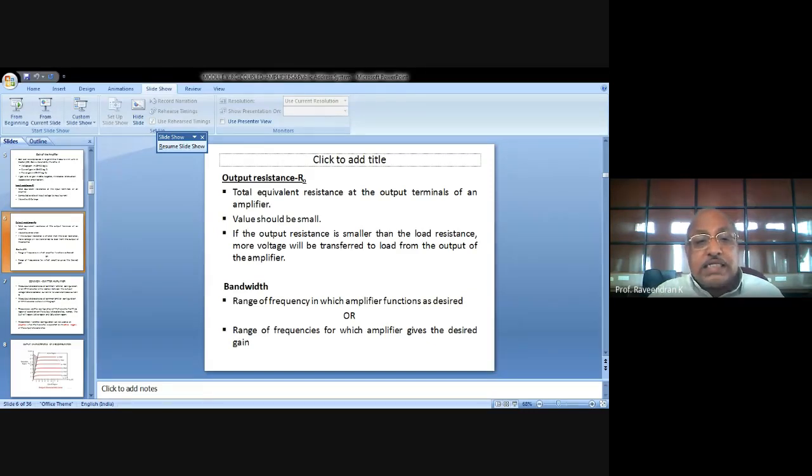So this resistance and capacitance network: resistance for the biasing network and the capacitance for coupling, the coupling capacitor. This resistance capacitance network is used to couple between the multi-stages of an amplifier for enlarging its gain. What for do we use multi-stage amplifiers? In order to improve the gain, so that the output will be a large amplified version of the input.